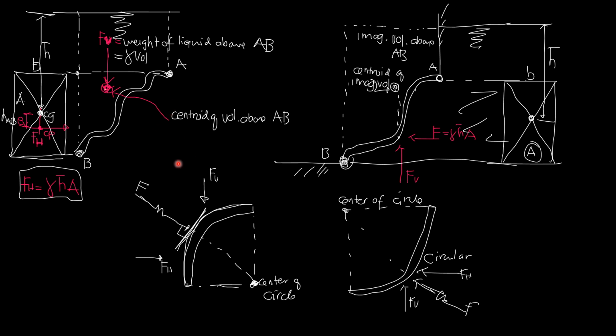Conical surfaces, for example, are also not constant. So in this illustration, the curved surface perpendicular to the board will have constant width, and I will call that width B. So if we position ourselves here, the projected area or shape of this curved surface, if it is constant perpendicular to the screen, would be rectangular.